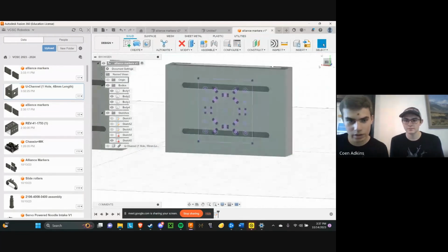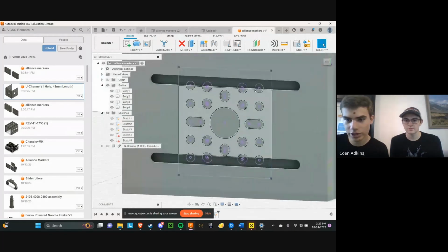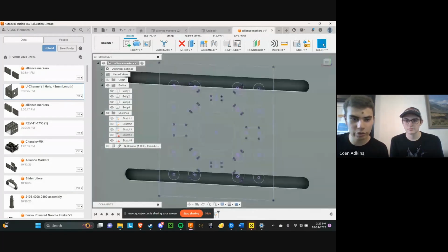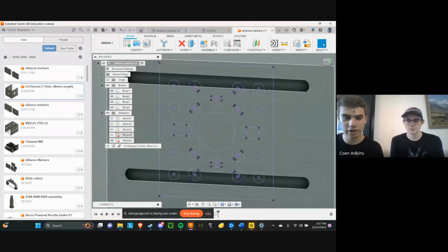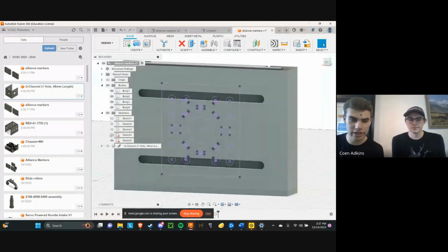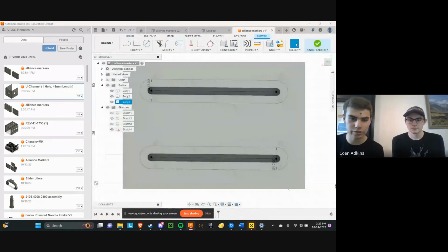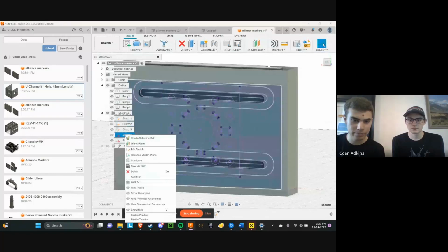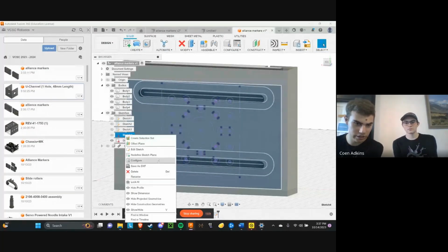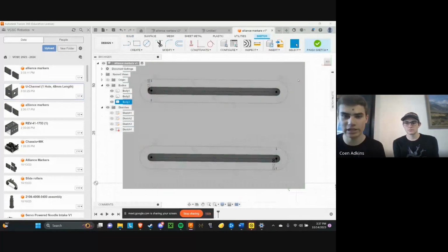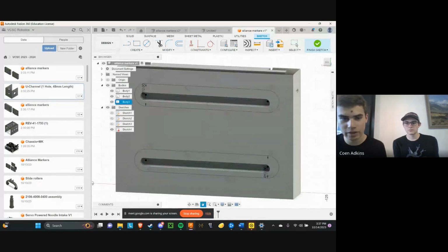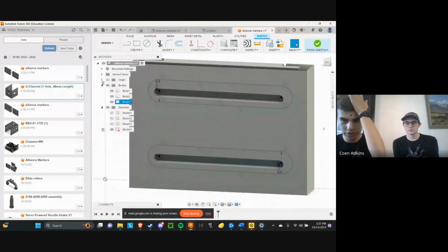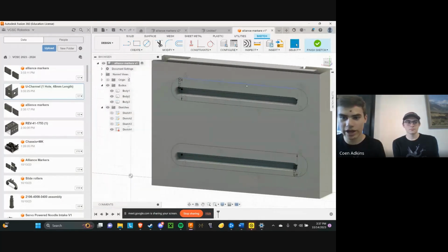Okay. And so in here, if you want to access a previous sketch before you added data, it's not going to be able to show your newly added data. So if we went back to sketch 4 and we wanted to edit it, you right click on it, and then it'll show this list here. The third one down will be edit sketch, and you can click on that, and it'll go back into that sketch workspace that we discussed earlier, and it'll show you what you did, and then you can edit it as well.